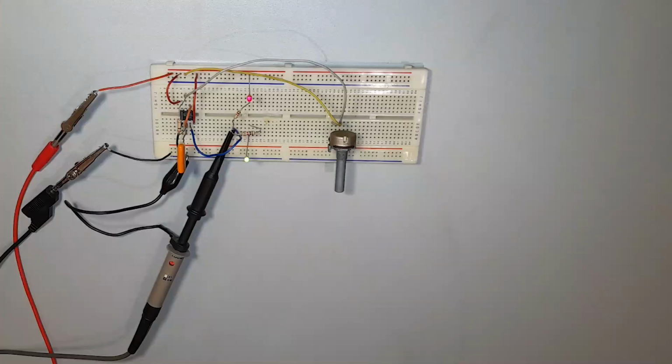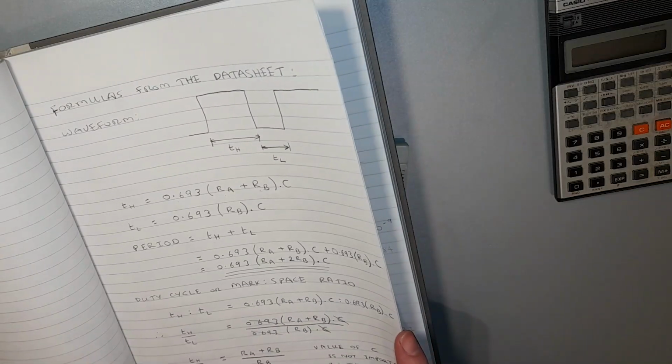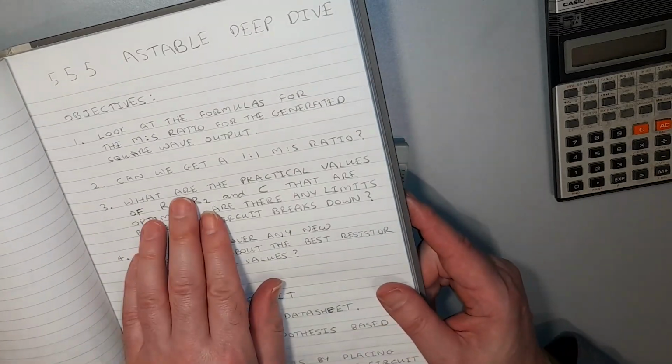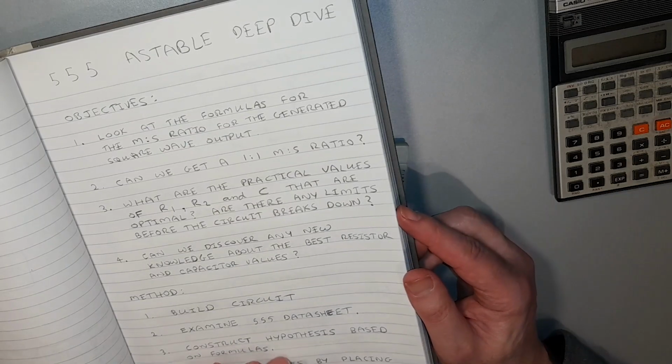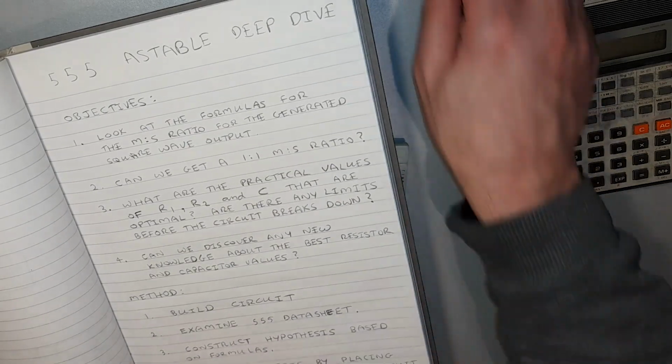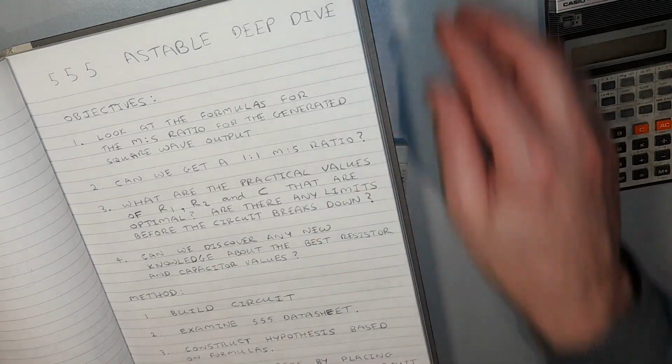So the adjustment here on the time per division, the milliseconds per division, this is the time base. We can adjust that to make it fit on the full 10 squares across, because we're interested in the mark to space ratio. We're not interested in actually calculating what the frequency is at this point. The goal, going back to our objectives, was to look more significantly at getting a 1-to-1 mark to space ratio. And you saw on the screen that we pretty much got that even before we'd worked out what the actual frequency was.